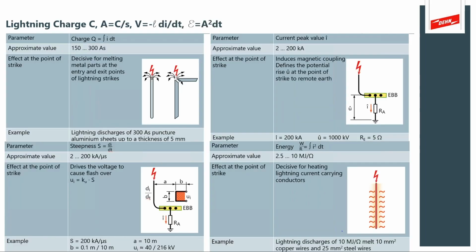So lightning charge is described mathematically in order for us as an industry to simulate and derive effective measures to protect. So how do we know a lightning rod or a down conductor is going to actually withstand what we say is lightning? This is a really important portion of the IEC methods, because all of the equipment in the IEC methods is tested with these parameters. And that way they're designed and tested, and the user knows that it's for the purpose of lightning protection.